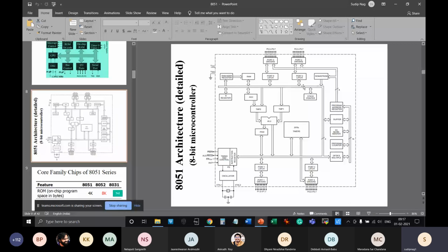And it will come to the data bus. So actually you are transferring the address to the data bus, temporarily. Then it will come to the buffer, and then through the buffer it comes to the program address register. Look at this, the program address register is an 8-bit register. So this is why 8-bit values are sequentially transmitted. If you have 16 bits to be transmitted, you have to do that 2 times.